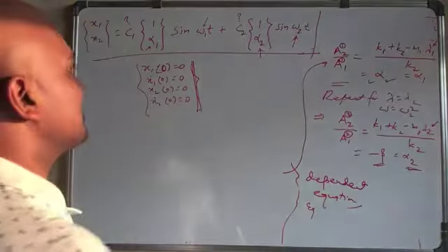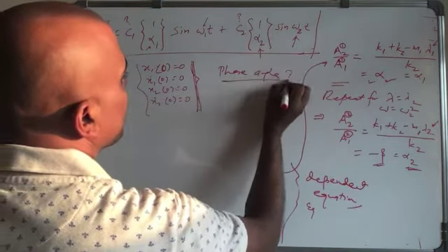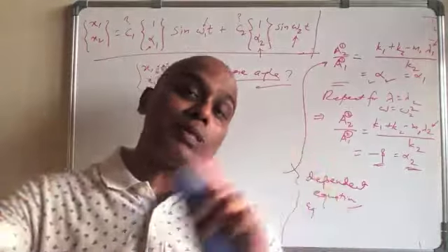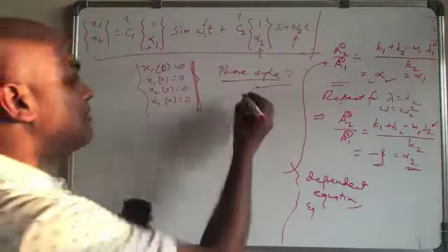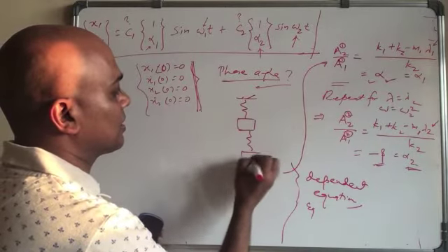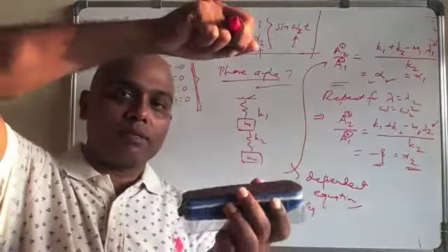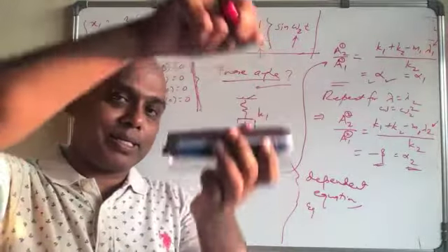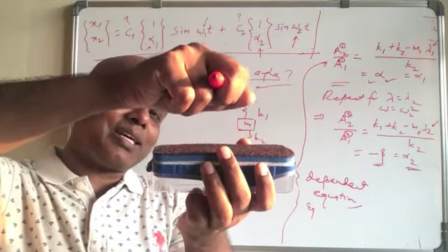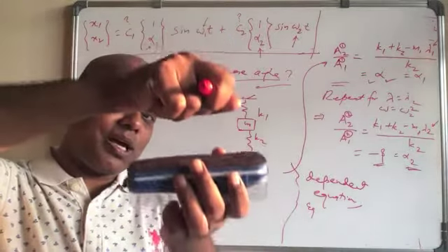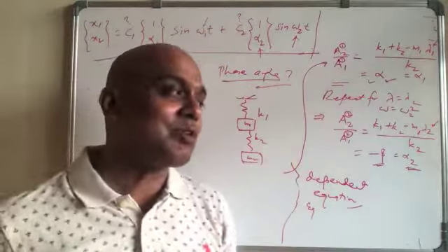You can guess it. Basically, where is the phase angle? Meaning there will be a combination of the 2 solutions, but there may be a phase difference between the 2 solutions as well. Let us say the spring mass system, this is K1, M1, K2, M2. You have started the first mode, both going down and up simultaneously, and they are somewhere at some phase. Then you have also added the second mode. There will be a phase difference between the 2. Accordingly, they have to be added together, right?